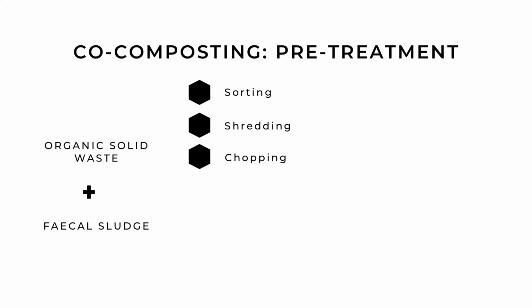Fecal sludge might contain solids such as plastics, rags, and other trash that need to be removed before entering the next treatment steps. These solids usually are removed by screens and must be collected and properly managed. Because the moisture content of sludge is usually very high, you need to reduce the water content to ensure aerobic conditions. This requires the use of solid-liquid separation systems and dewatering.